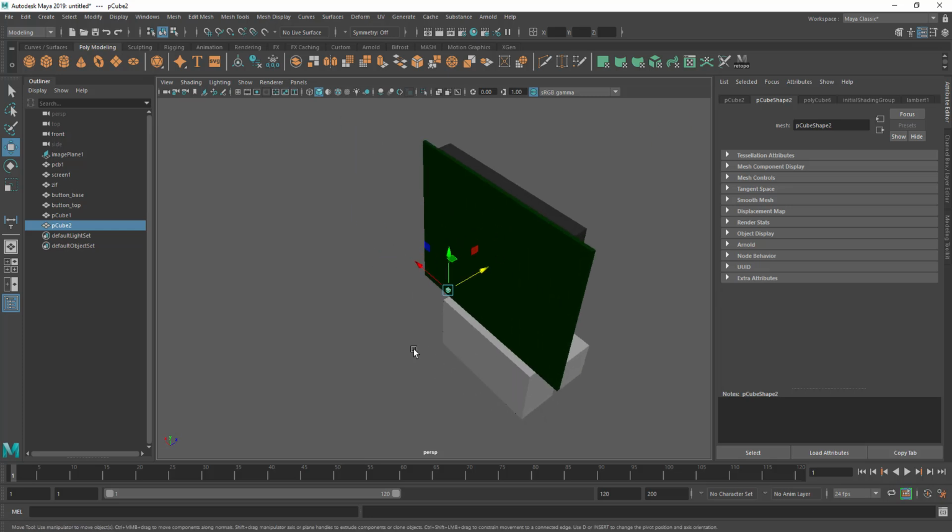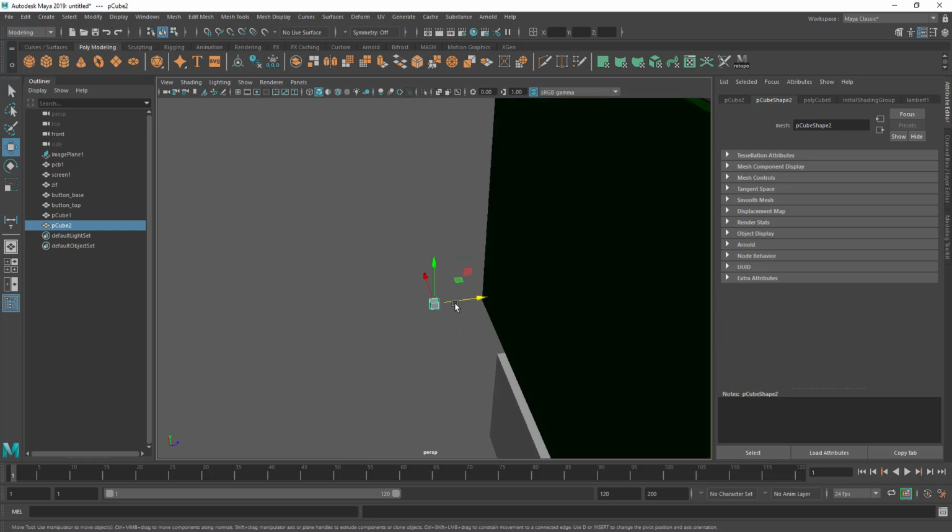Now before I do that, I do want a maximum width to this. The optimal width for my 3D printer is 0.28 millimeters if I'm going to print the case as strong as I possibly can. So let's say I wanted 7 layers. For rigidity I need 1.96 millimeters, or 2 millimeters should be close enough.